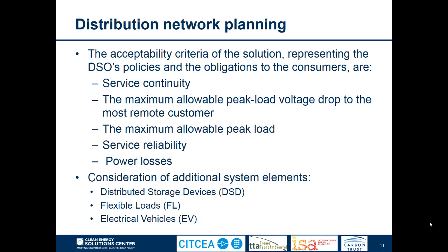Another possibility is to use flexible loads, which can be connected or disconnected, or sometimes adjusted to a different power level depending on their needs in the system. These flexible loads can be very useful and can provide a service very similar to the one provided by energy storage systems. One specific type of flexible load is electric vehicle chargers. We can optimize when we are going to charge the vehicles, and by optimizing that we can achieve a better integration of the solar PV and also better system functioning.